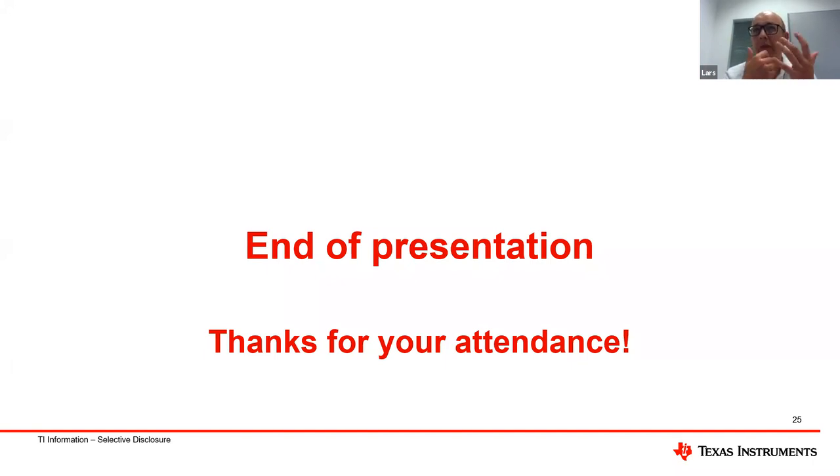So you may now think, okay, I can maybe put two resistors in parallel in this resistor divider, so when one opens, the other is still having a certain voltage division. Whereas the higher leg, the horizontal resistor of this resistor divider, if this opens, then the lower resistor just connects the other circuit to ground, which could be a safe state.